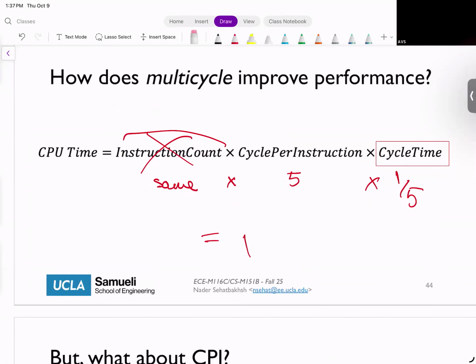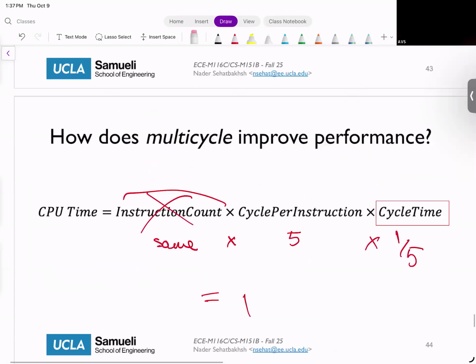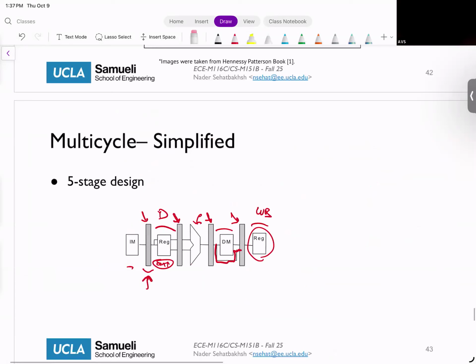Yeah, updates at the same cycle. Because, so it's like this, right? Your instruction comes to the instruction memory. It updates this value, but the registers are not transparent. They get updated in the next cycle, right? So you start from here, this value gets updated, this value gets updated, but then it waits until the next cycle comes.